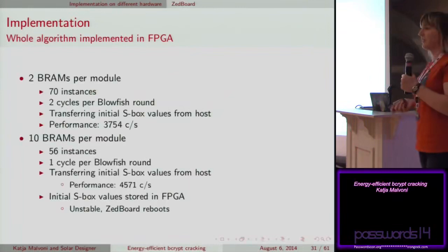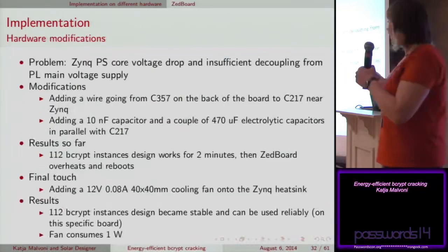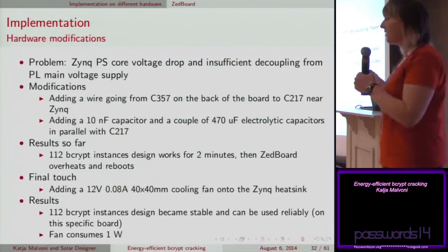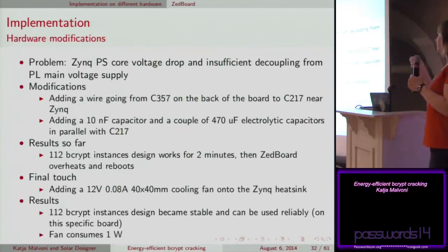So we saw that all the designs look nice and promising. They actually do not work on real hardware, so we modified it. You don't really have to read all of this. It's important to notice that there was a problem with voltage drop, and there was a problem with insufficient decoupling.